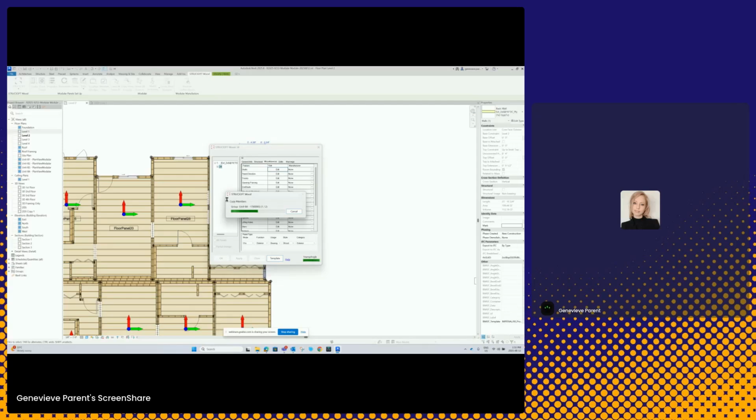And of course, a good setup prior to this is always, always important. I can't stress that enough. When it comes to Revit modeling and how you want everything to come out when it frames, it's very important to model everything the way it's supposed to be modeled. Meaning it does have to make sense if you have gaps, spaces between your modules, or if you don't. It's very important to consider how this is going to be framed as a unit.